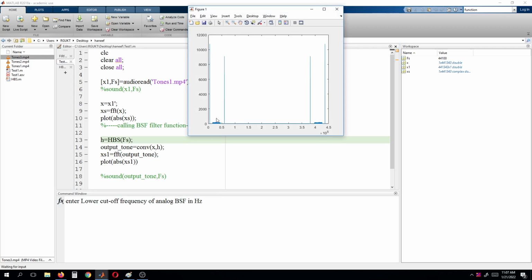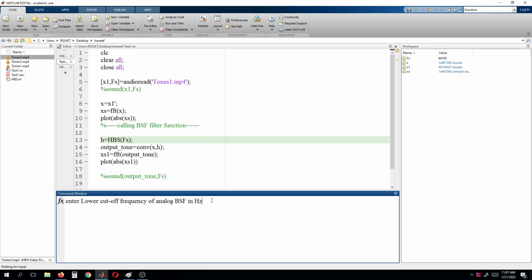It is showing that the noise is available here. We have calculated the cutoff frequencies and the frequency components. The first frequency component was 500, so it has to pass. We'll increase the cutoff frequency to 1000, and for the upper cutoff frequency, our frequency component is available at 6000, so we'll give the upper cutoff frequency as 5500, and the length of the filter we'll give as 555.